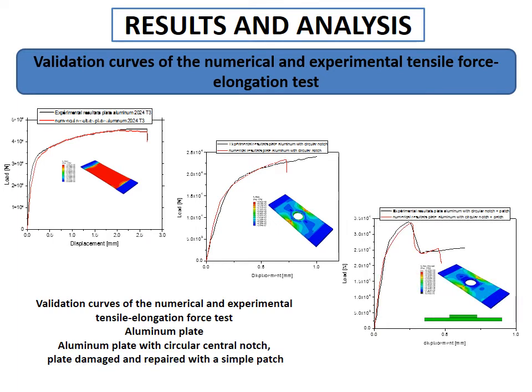For the validity of the numerical model through the study of the sensitivity of the mesh, through our study by the three-dimensional finite element method and by the use of extended finite element method and cohesive zone model techniques, we could analyze the damage of the structure repaired by the automatic propagation of the crack in the plate and the debonding of the adhesive. The validation of the tensile curves carried out on the structures repaired and not repaired by composite patch became practical when one uses these two techniques while ensuring a good choice of the density and the types of mesh elements.